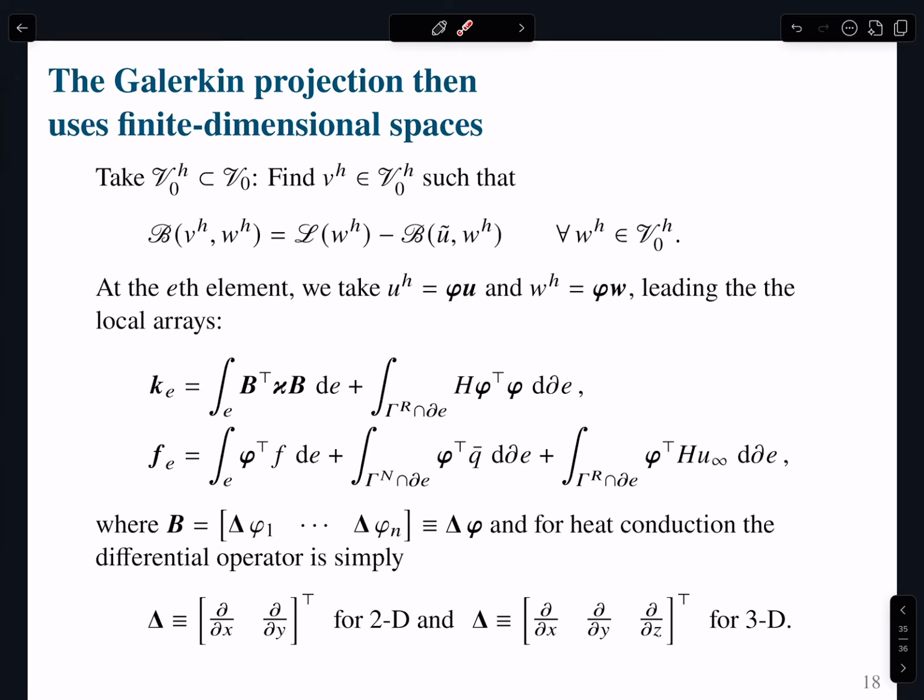What is the size of that vector? It's 1 by 3. Triangle has 3 nodes. Yeah, so it's a 1 by 3, and this is my local temperature vector that is size. What is the size of that? 3 by 1. So I have a 1 by 3 multiplied by 3 by 1. I get a 1 by 1. It's like I get my scalar field inside the triangle, right?